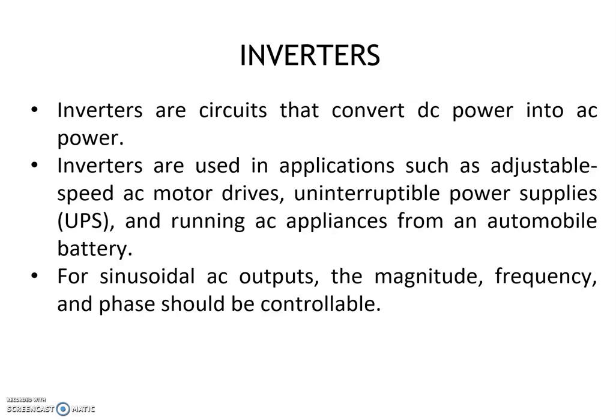But we can't use this phase controlled rectifier as an isolated independent AC voltage source, because it needs an AC supply at its input for commutation purposes.